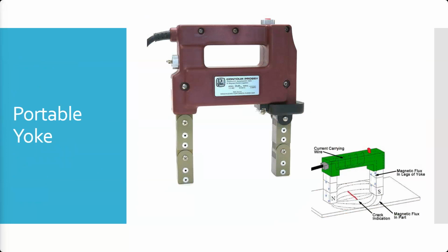It also is things like windshield frames. We'd have to do the windshield frames so that it wouldn't mess up the whiskey compass that was at the top of the windshields. If there was magnetic hardware in the wing area, flap tracks, the tracks and the hinges for the flaps and the ailerons, those could get magnetized. And those are out near the flux gates for the navigation systems that sense the Earth's magnetic field. You don't want to have a big magnet right next to the sensor that's trying to sense the weak magnetic field the Earth produces. So, this had multiple uses.